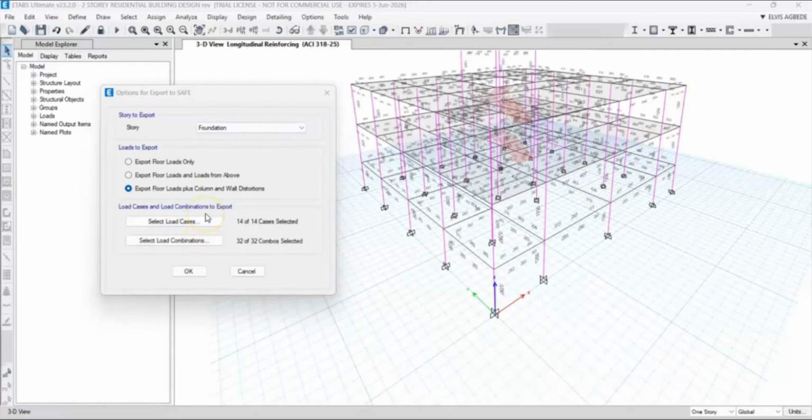We tend to use this for super tall buildings and high-rise structures, let's say 30 stories and above. This is where your cumulative column compression adds up significantly and tends to induce secondary bending stresses in the foundation raft. So that is when we can use this. But for normal structures, we tend to go with this.